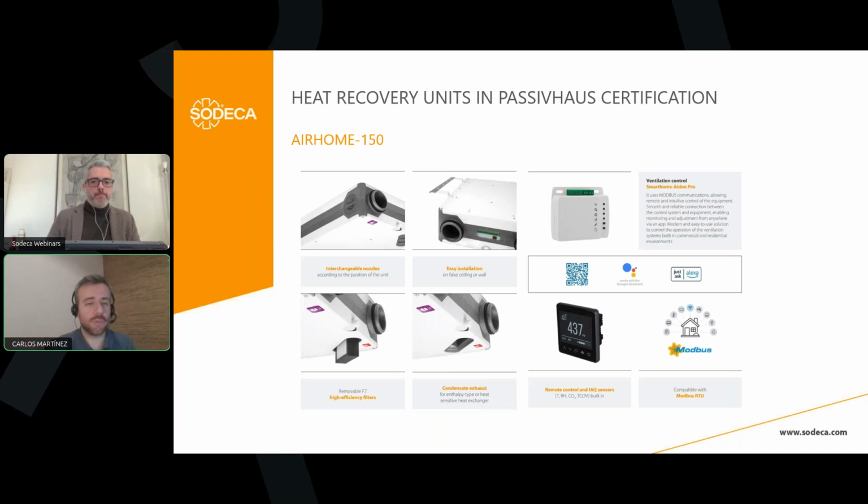So for us, it's very important that this indoor quality sensing is reliable. So we can control and modify the velocity of the fans and the total flow we are delivering by following the concentration of carbon dioxide, which is very related to the presence of people, and also the concentration of volatile organic compounds. That's an amazing characteristic that we are using.